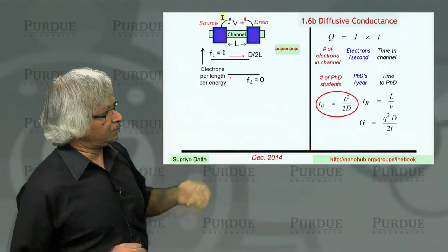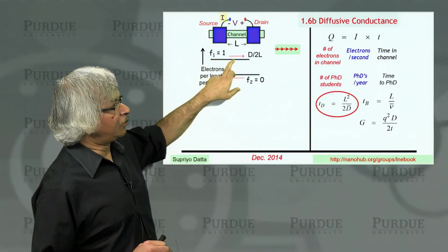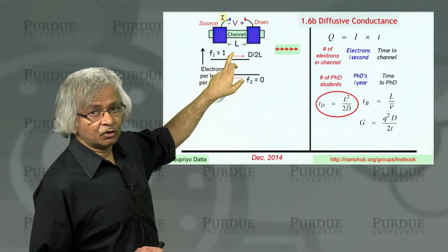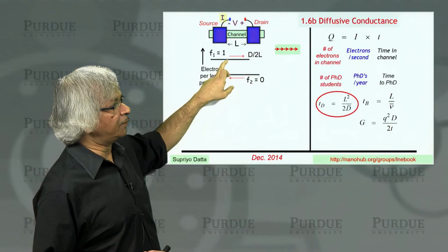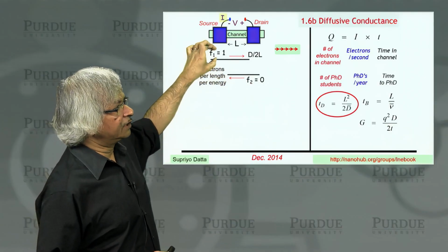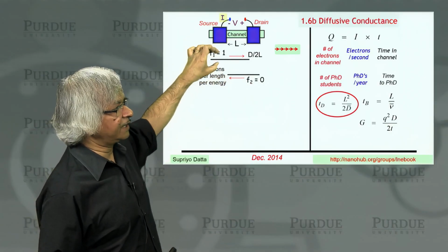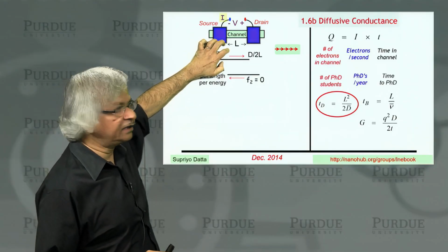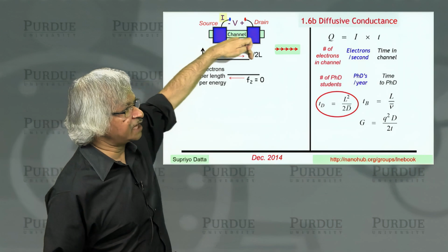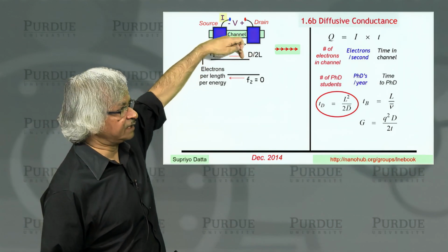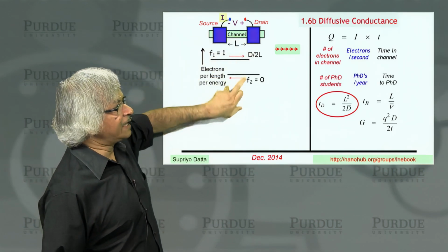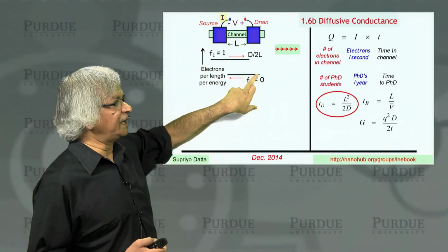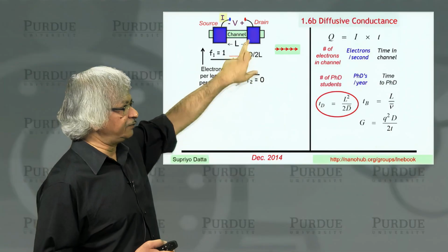For ballistic transport, we can say that all the states that are carrying current from source to drain will all be occupied if, let's say, the Fermi function in this contact at this energy happens to be 1, which means if all the states here are filled, then all the states in the channel will also be filled because they're all coming from here. Whereas the states that are carrying electrons the other way will all want to be empty if in the contact the states are empty.